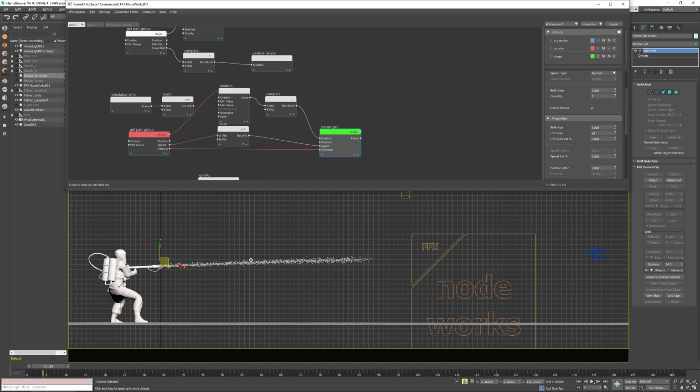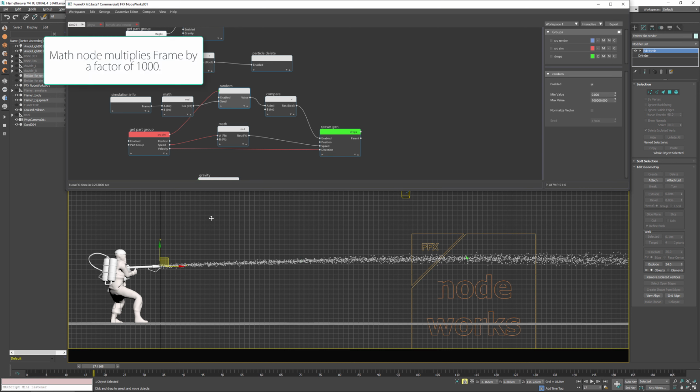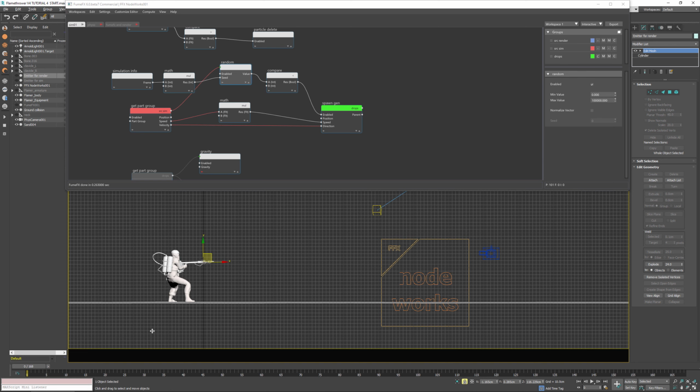So how can we add some more randomization here so that one particle can be activated and converted into drops at any frame? We need to change this seed number, so each particle will have a slightly different seed number on each frame, so it's actually generating a different random number on each frame.